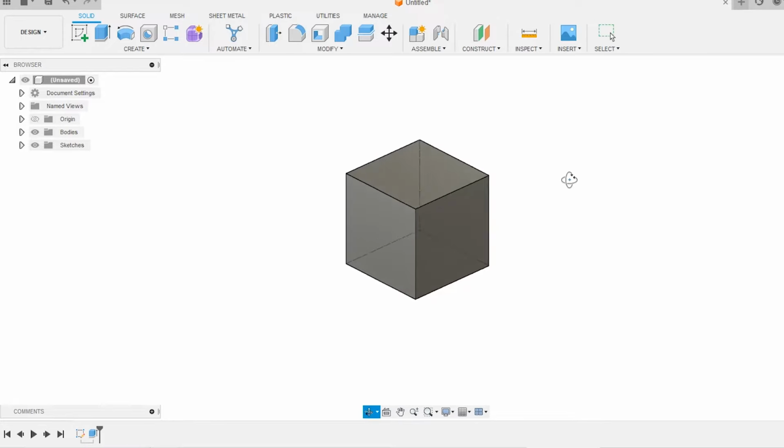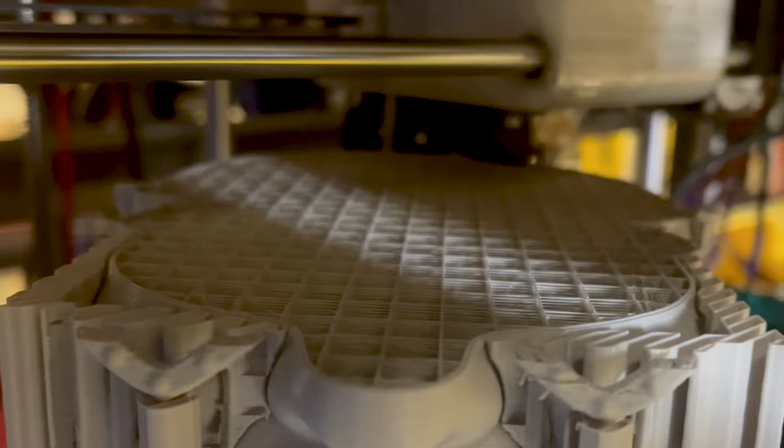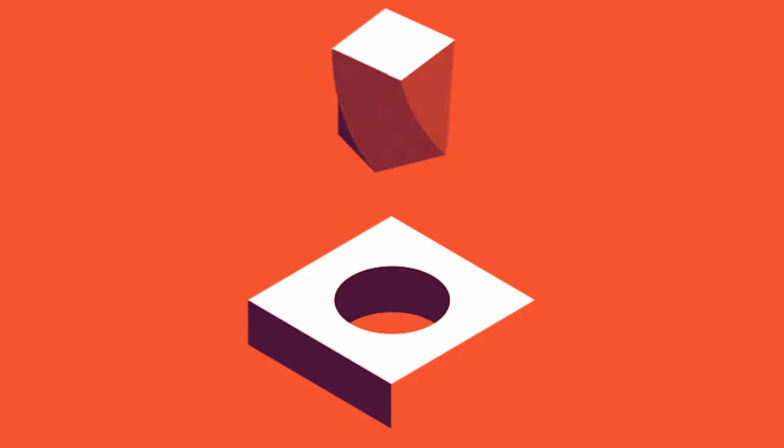A theoretical client wants to come to us and make a 50 millimeter brick, and they want to know what it would cost to do with injection molding or with 3D printing. Well, first of all, we tell them you have to design for the end process, because putting a square peg into a round hole will not work. If you have an injection molded design, it should not be 3D printed. If you have a 3D printed design, it should not be injection molded.